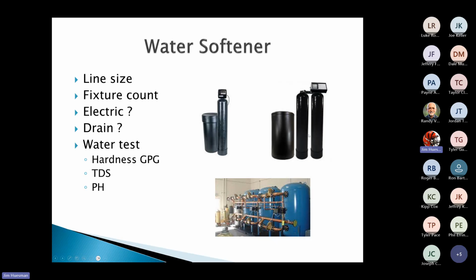And the only reason you do that is when tank 1 goes into regen, automatically the tank 2 will kick in and provide water. So again, a building that's occupied 24 hours a day, you're going to need a 2-tank system, or you'll start getting complaints that between 2 and 4 in the morning, their water volume is almost down to 0. And that's because the water softener is going through a regeneration period. So just make sure that we understand that one.